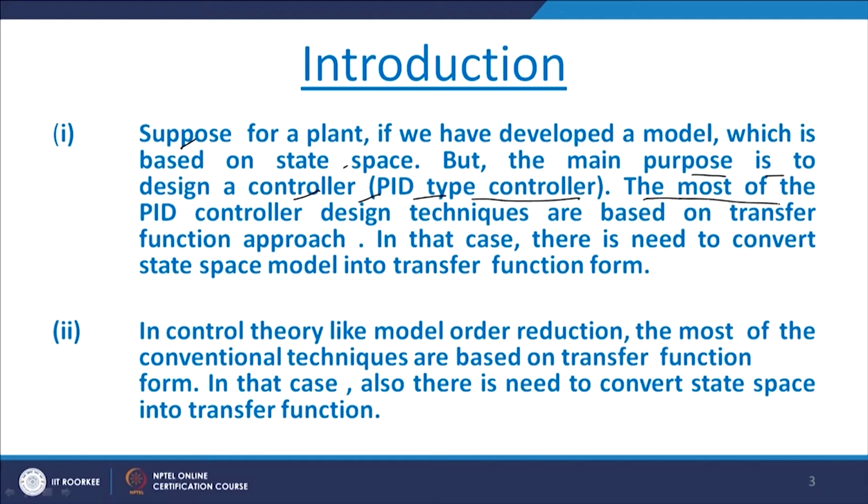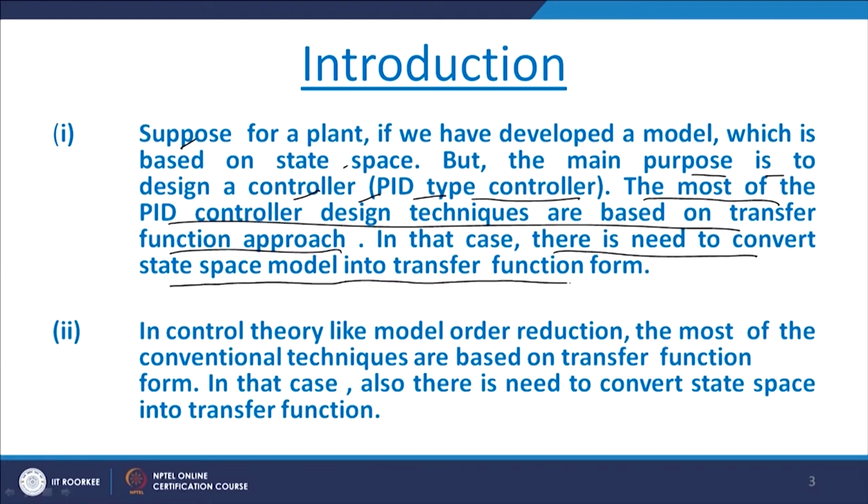Most PID controller design techniques are based on the transfer function approach. The researchers have developed various tuning techniques, that is, tuning of PID control parameters, and they are based on the transfer function approach. Therefore, in that case there is a need to convert the state space model into transfer function form.